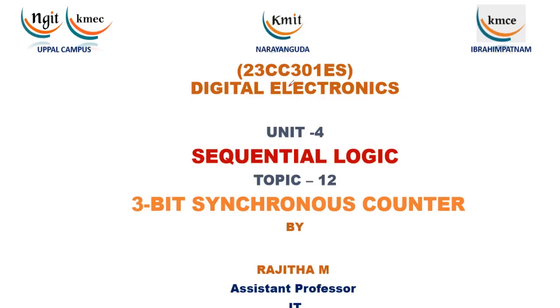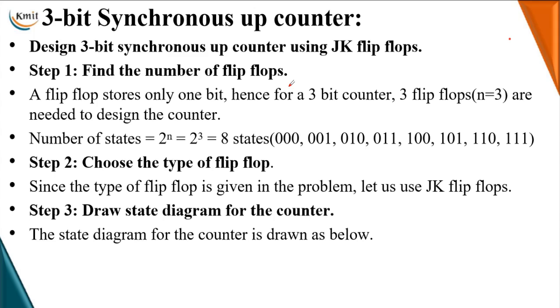In today's session, we learn about how to design a 3-bit synchronous up counter and down counter. In the last session, we learned about the 2-bit synchronous counter, how to design the up counter as well as the down counter. The same procedure we are going to follow here too. The only difference is we are going to add one more flip-flop to design a 3-bit up counter or down counter. Since it is a 3-bit counter, the number of flip-flops is 3.